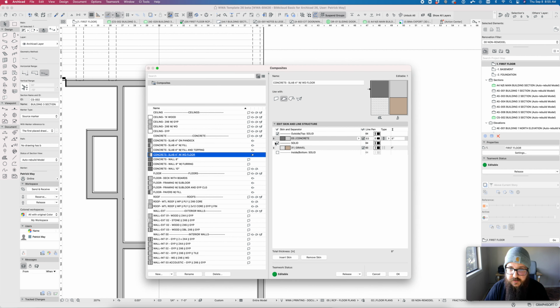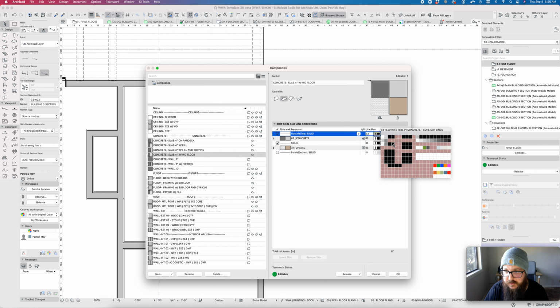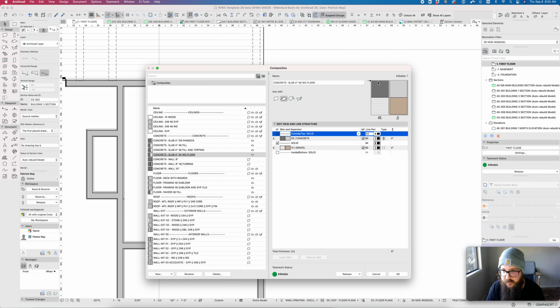This is just sort of an example of something that might happen. So here I've got the pens already set up. I've got the building materials already set up. So these are the divider pens, the top pen right there. If you remember back talking about the pens, we mentioned that this core pen would be for concrete elements. So pen 64 is the top and the bottom pen of this skin in the composite settings. The gravel fill on the bottom, and then there is no under pen on this particular composite. That's been unchecked here.